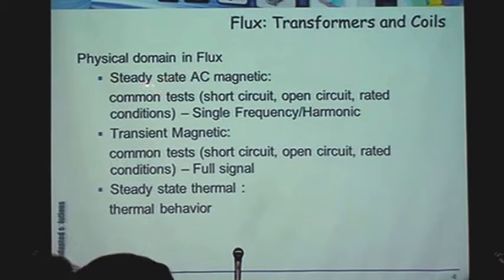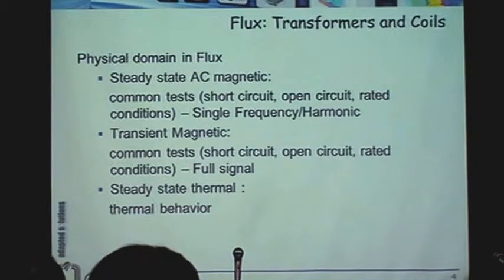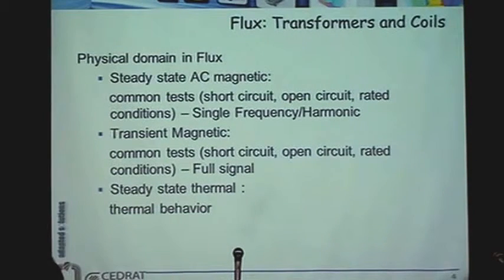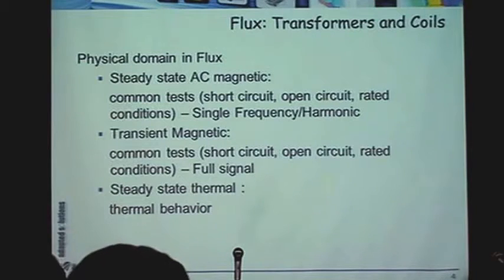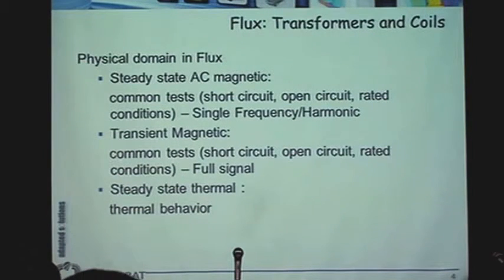We're going to do the study in steady state AC. Regarding the difference between steady state and transient, sometimes we cannot use steady state. If we are very interested in harmonic effects or things like this, or saturation, if we want very, very accurate saturation, sometimes we have no choice but to go to transient magnetic. Steady state AC will assume that all the signal is sinusoidal. But if you really think about it, in transient, in nonlinear, the flux density variation is not sinusoidal anymore, it's an ellipse. So it's not going to work so well.